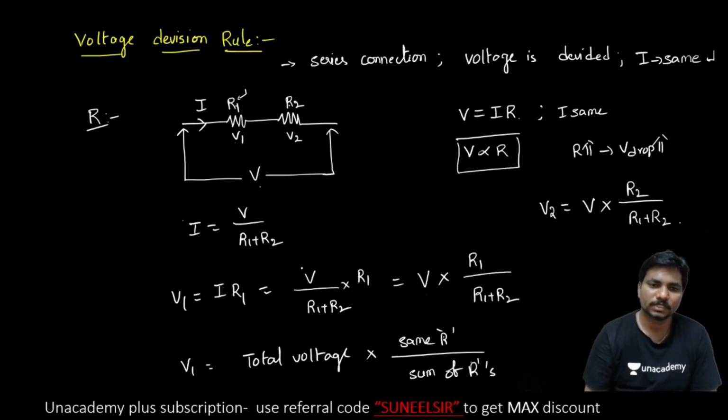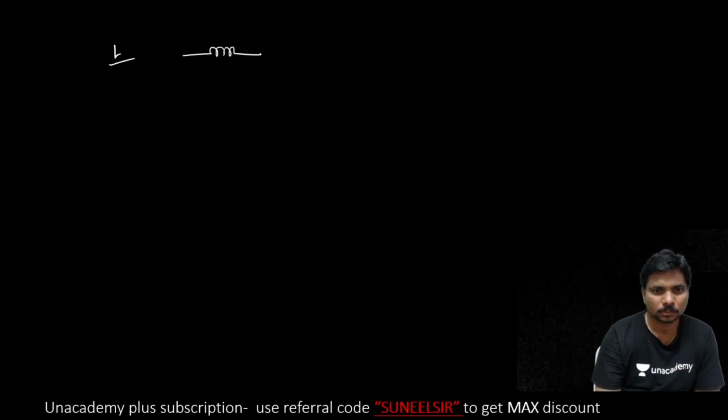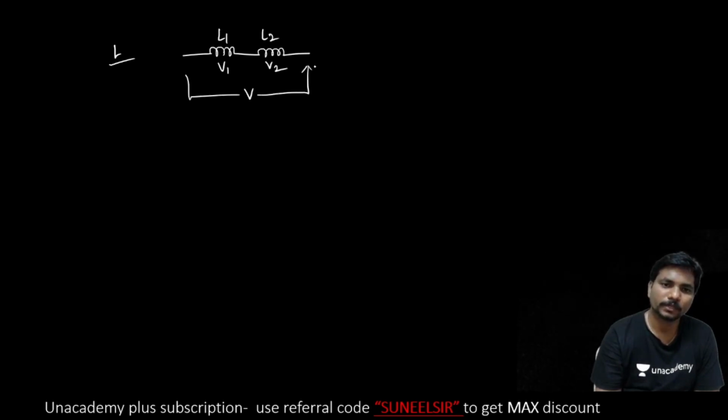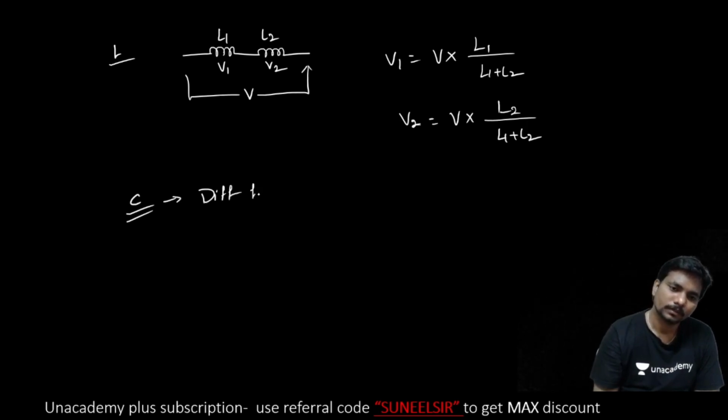The same voltage division rule holds for inductors also. If you consider inductors L1, L2, and you apply the total voltage, it is V1, it is V2. V1 is equal to total voltage into the same inductance by total inductance. V2 is nothing but total voltage into the corresponding inductance by total inductance. But coming to the capacitors, the formulas are different from resistors.